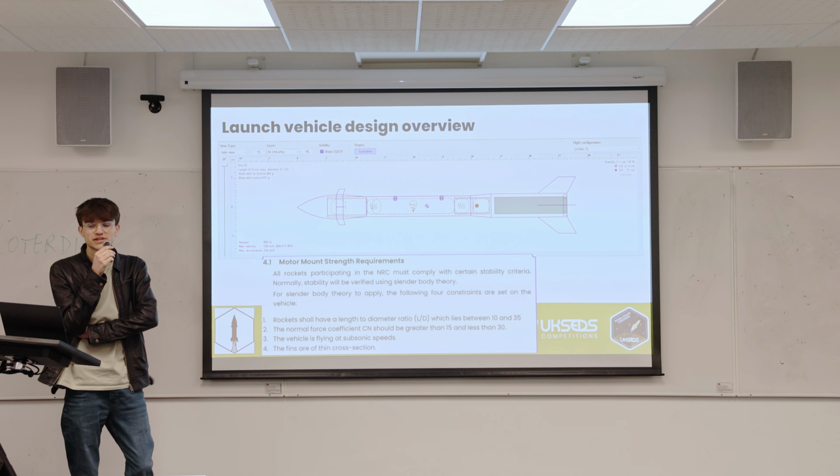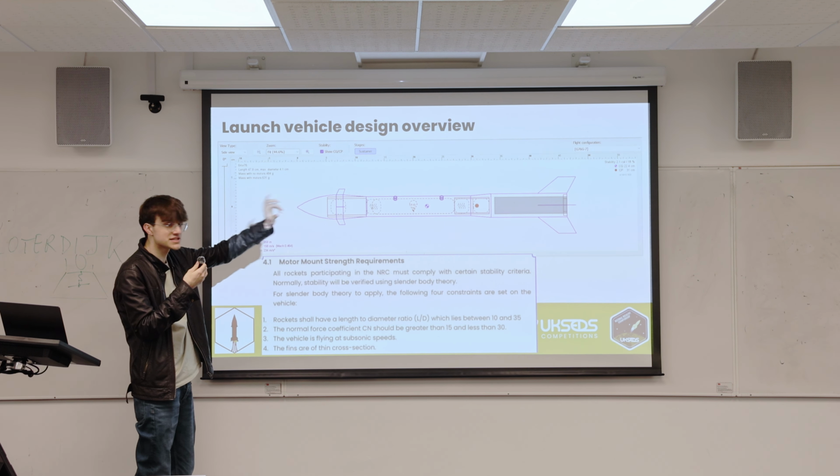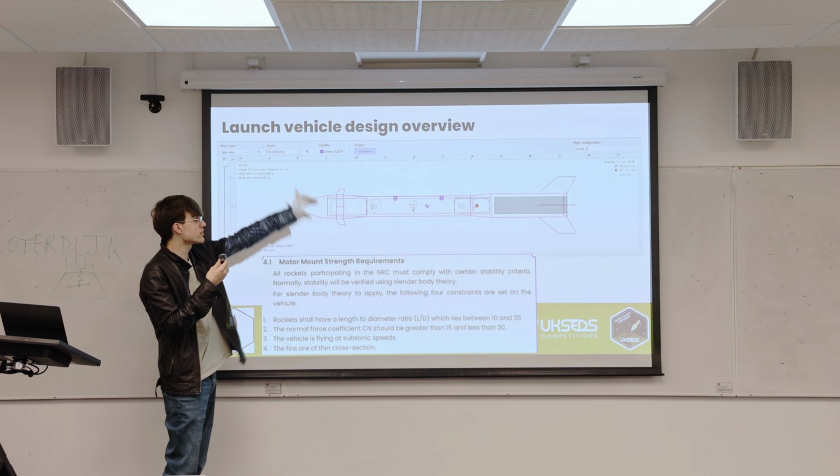So in our rocket, the main thing we have gone with is a canard design for active aerodynamics. This allows us to change the rocket's trajectory. Stuff we've made sure to emphasize, so it meets technical regulations as well, is the fin height. So the fin height in this design has been iterated to be optimal. If we increase the height of the fin, that gives us more stability. However, we are limited in that by the technical specification.